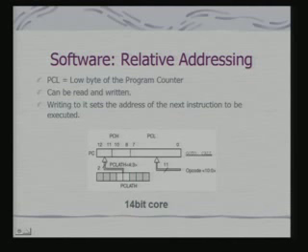Whatever offset is coming is an 11-bit offset which is part of the instruction. So, all your goto and call operations are PC relative. This is the key significance of the fact that the most significant bits are coming from the PC latch high register.